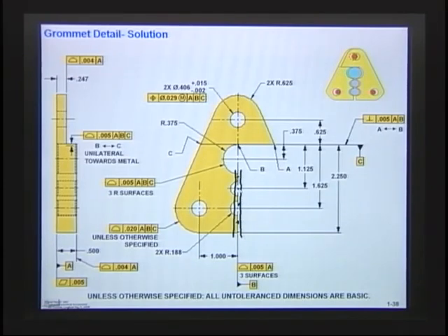If they touch more than 2 points, they're going to get a number of points. You're going to collect data on this surface, and they collect that data. Now remember, what they're supposed to do is come in and move to the high points, right? Because that's what the datum is. Remember, that's what the designer is calling off. So they would have to come in, and once they found that that surface fell within that profile of 5, then they move to the high points and they establish the first plane.